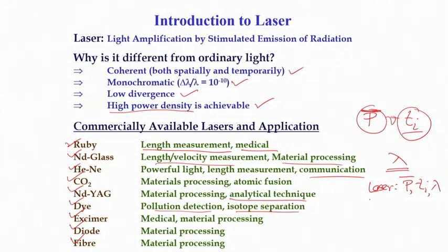The other part that will govern the selection will be the various material properties. These material properties start all the way from specific heat to melting temperature, then reflectivity, thermal conductivity, and various kinds of physical and mechanical properties of the material.